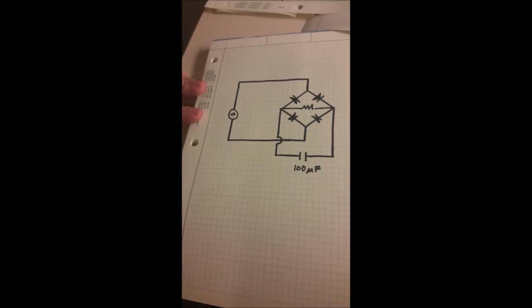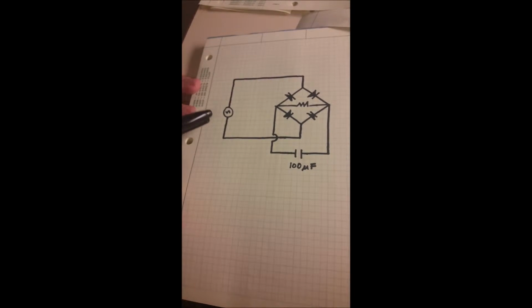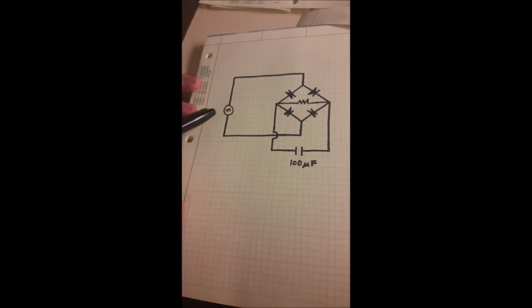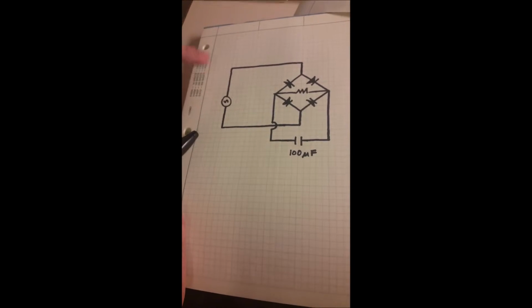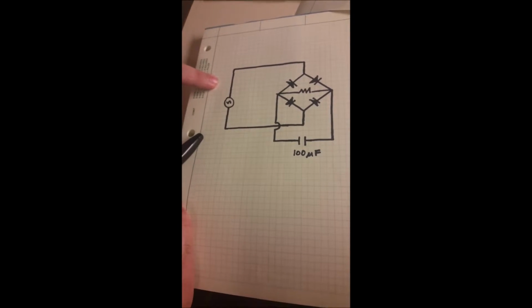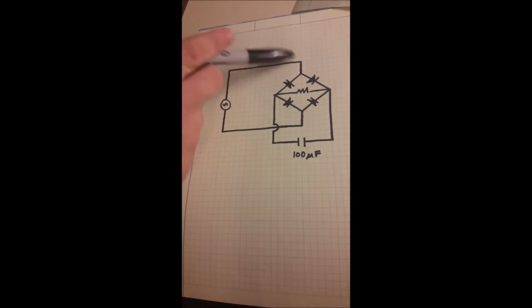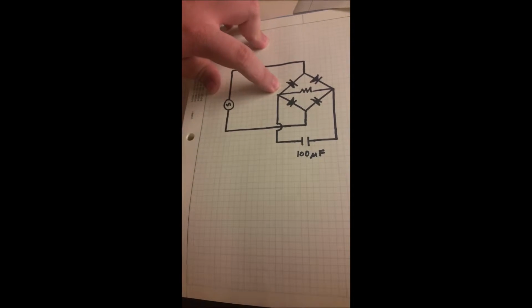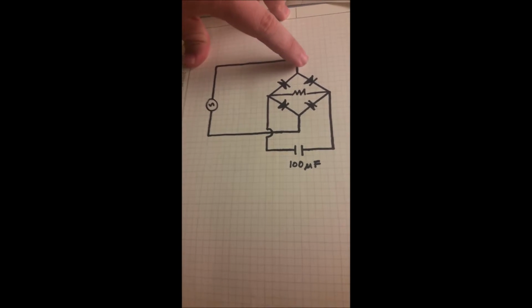This is going to be a basic schematic of a rectifier that we talked about previously. This here would be an alternating current source. Notice the squiggly line in the center of the circle. So as time passes, the direction of flow out of this is going to alternate between positive being on top and positive being on bottom. As the current comes around to being on the top here, these triangles denote the different diodes. Diodes only allow current to flow in the direction that the triangle is facing.